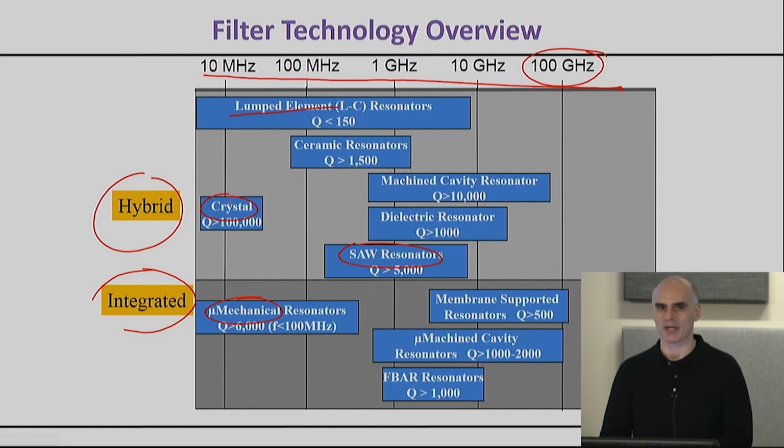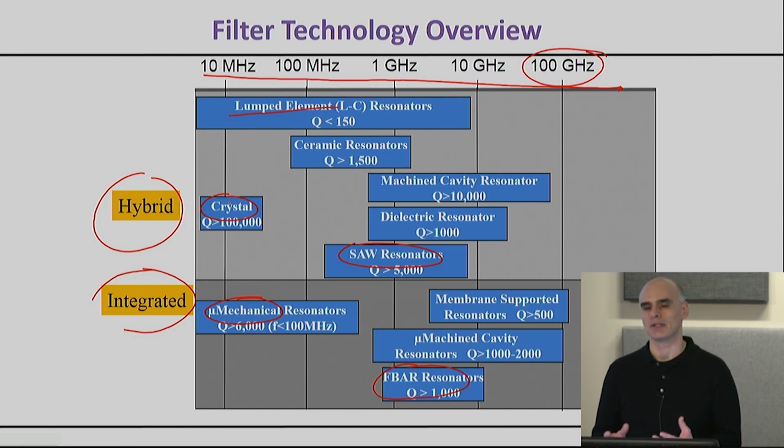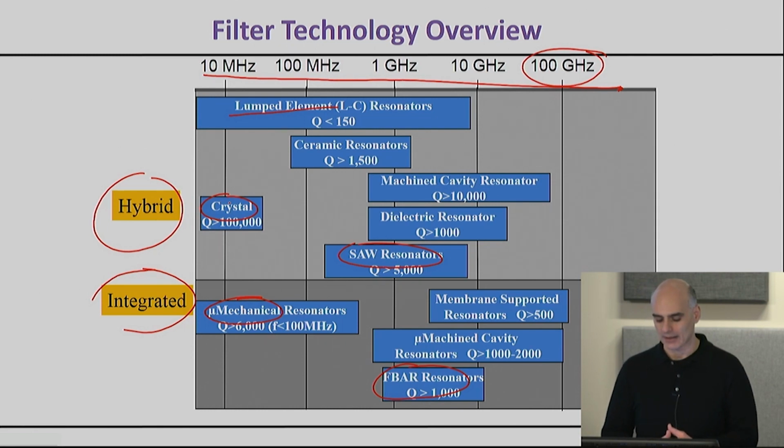That's why we have micromechanical resonators or surface acoustic resonators or bulk acoustic resonators, like for example the FBAR resonators. It turns out that mechanical resonators are actually amazingly high quality, and at the same time they're very, very small. So there's a whole family, which we'll try to cover a little bit later on, that basically relies on acoustic resonances. And that family has produced some of the best filters in the world. In fact, our available filters today for cell phones are basically acoustic filters.